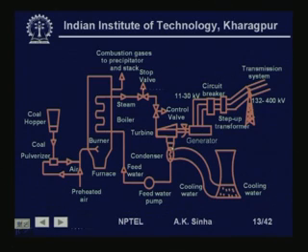The water which comes out from the turbine is sent to a condenser where it is cooled, and this condenses, and then through a feed water pump it is again recirculated in these water tubes of the boiler, and this is a closed cycle, because here we need to use very pure water, otherwise the tubes will get clogged with the residues which will get stuck to them.